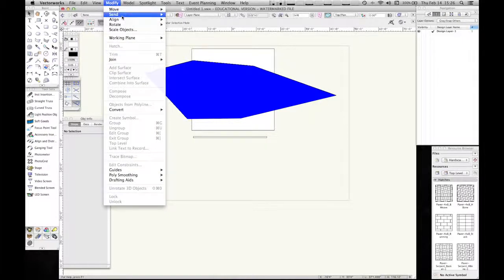The difference between these is very simple. Send to back means you send it to the very bottom. If you have 12 objects, it will always be this very bottom. Send backwards means you just go one below. So if you have 12 objects and your square was your first object, when you hit send backwards, it will now be your second object in your stacked layers of objects. Send to front and send forward do the same thing.